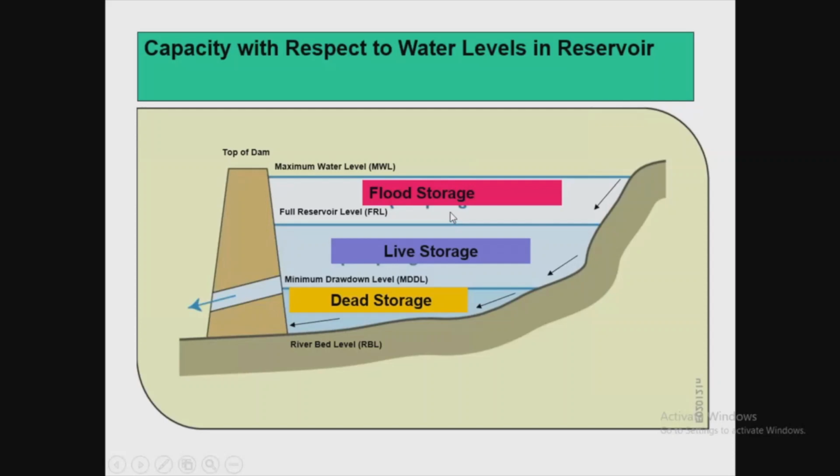So for that purpose it is kept, but we will restrict our capacity to this part only, the live storage portion and the storage up to the full reservoir level. So before going ahead, this is the capacity of the reservoir we are taking into account. Suppose it is X million meter cube. We have to assess this capacity in the present scenario. Suppose the particular dam was built in 1950. Now a number of years have passed.